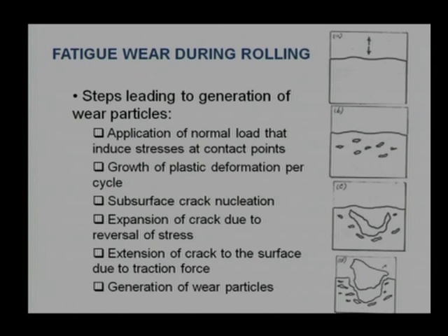That is why stresses will be generated in a perpendicular direction, this direction and this direction. That is why the crack is nucleated and expanding towards this direction. It does not come directly under the load, it is going beyond this side and this side, because of the lateral force or tensile stresses in the lateral direction.